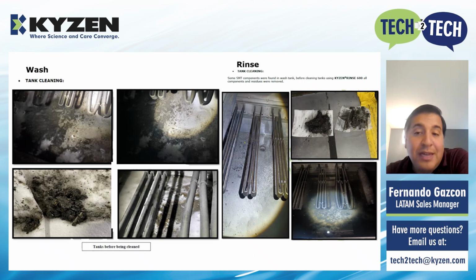We also found a thick layer of mud on the bottom of the tanks, consistent with the same mud-type residue found in the spray bar nozzles. Many electronic components were found in the bottom of the wash tank and rinse tanks that had fallen from boards that were being washed through the process. Due to the state of the washer, we recommended performing a complete cleanup of the system to remove all contamination accumulated in the system, which was causing all kinds of issues like the ones previously described.